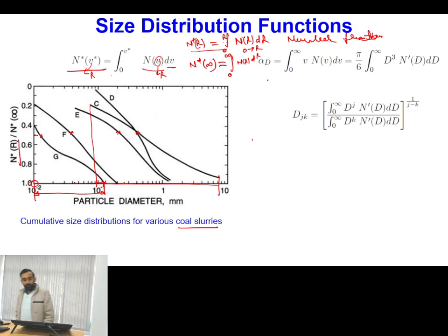Okay. So later on I will give you some idea about the turbulence present in multi-phase systems which have particles. If the sizes of particles are below a certain critical limit, then if any turbulent fluctuations are present in the system, particles simply follow the path of these turbulent fluctuations and they try to stabilize the flow.